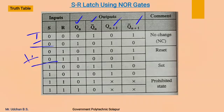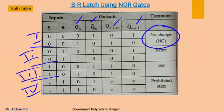This is our case 2, this is our case 3, and this is our case 4, which we have discussed already. For S 0, R 0, output will not be changed. For S 0, R 1, the output will be in reset state.